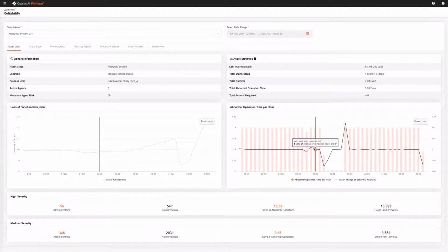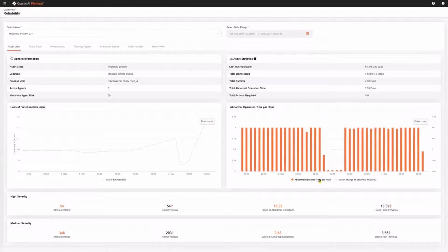And when I say fail, I don't necessarily mean a catastrophic failure, where it blows up or completely shuts down. But failure means an asset can no longer perform its designed function. So the asset may still be running, but if it isn't running as efficiently, or with as much load or throughput as expected, that is hindering your process and is considered a failure. So your asset risk is how likely your asset is to fail or to no longer meet its design capability.